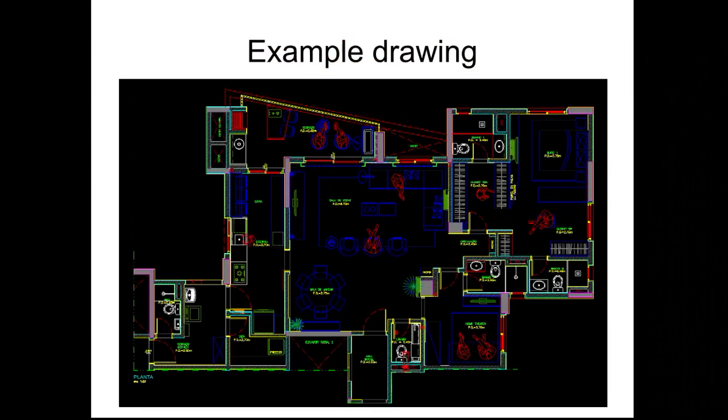But to draw all these things separately in different drawing files is not really the solution. All of these different elements can be drawn on one same drawing using the Layer tool. With the Layer tool, you can choose the elements that you want to see in a drawing. Layers can be used to control the visibility of objects, as well as to assign properties such as color and line type.